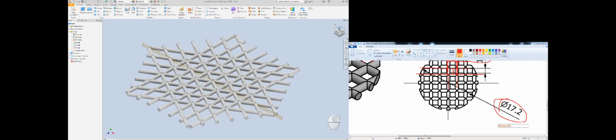As you see, we can create the first mesh from the top side. Start a new sketch on the XZ plane. To make a cut at this point, I will use the origin point for the cut section, and also this donut area, this profile, for the cut selection.